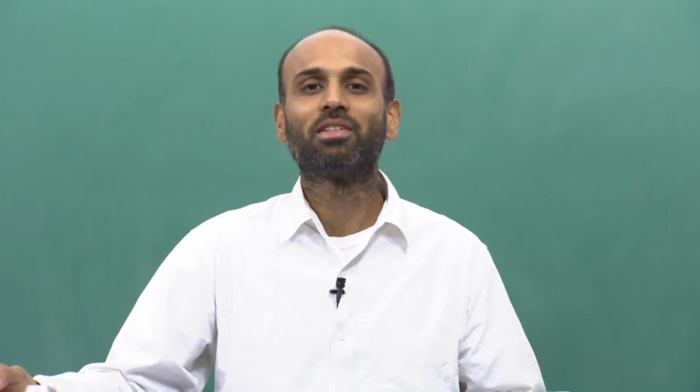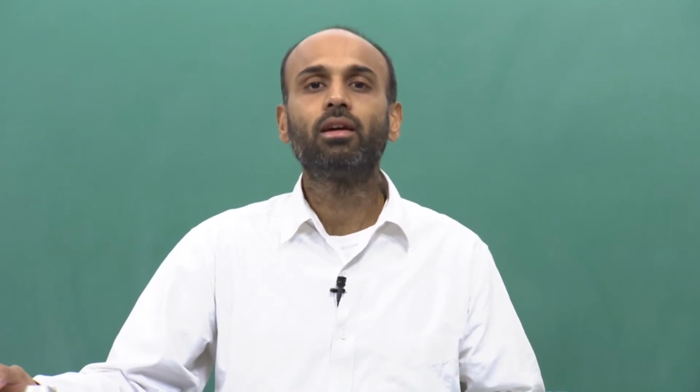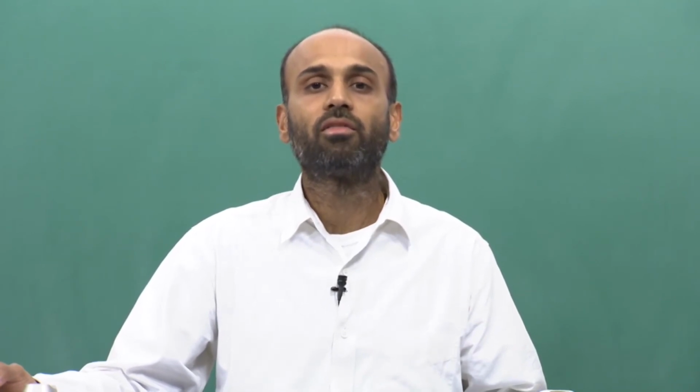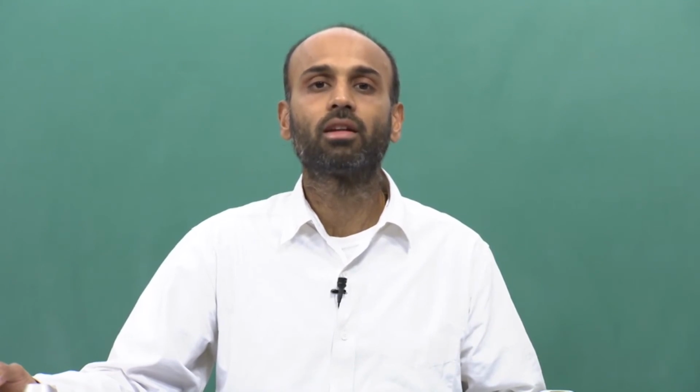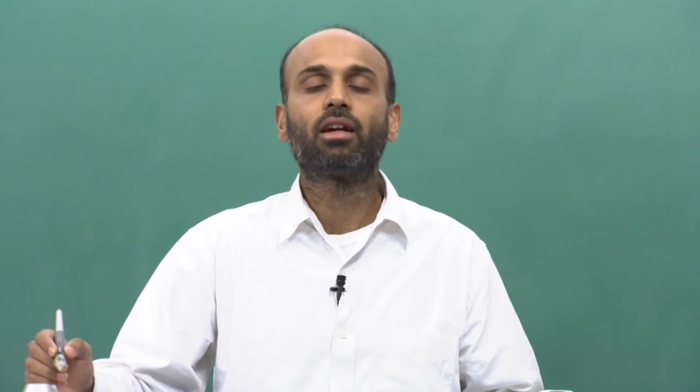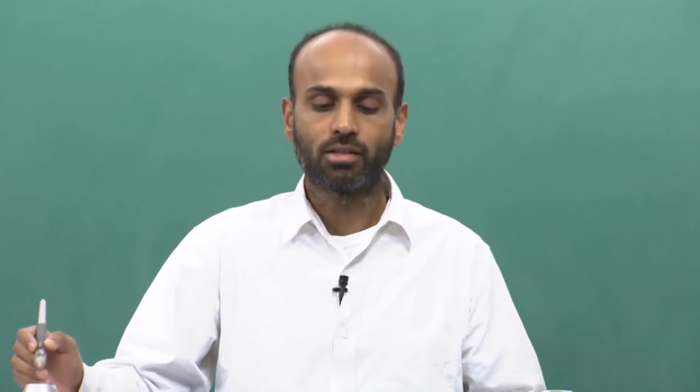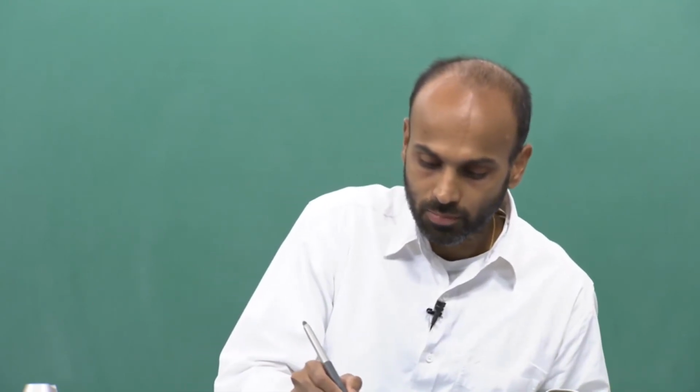Welcome to another module in this massive open online course on MMSE estimation for wireless communication systems. So, we are looking at the linear MMSE estimator, that is the linear minimum mean squared error estimator, also known as the LMMSE estimator, and we are looking at finding the optimal weighting vector, that is the combining vector C bar. We said that if we have a function f of C bar, a function of the vector C bar, then the derivative with respect to C bar,